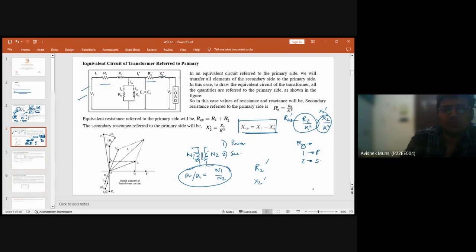From the phasor, we can see that this is in the reverse side, so it will be negative. In the circuit we have to add it, but when doing the complex number equation solving, you can see that it will be a minus j component. Basically, whenever you are getting the impedance, it will be like R plus jX. So for the introduction of the j imaginary term, it is putting a minus over it.